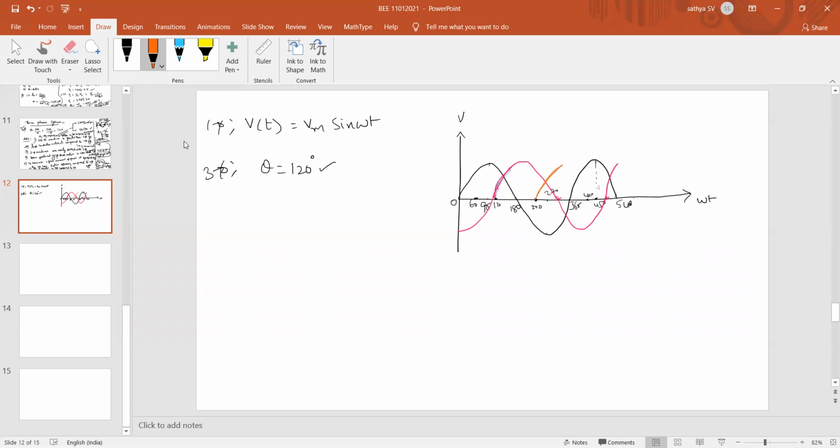Yes. So where we need to end up at 120, you need to make the equal magnitudes while you are drawing. Equal magnitudes in the sense, this amplitude value you make as an equal amount since it is a balanced system. So from this 120, where should it extend to, the next 180 plus 180. See here, shall I extend it to the backside for this, 240 minus 180? Minus 180 in the sense it should be 60.